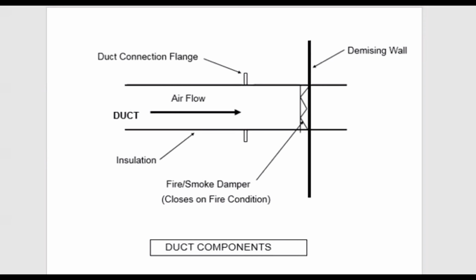All right, so if it's 50-degree air that's coming out 5 feet away from where you pass through the cool water, you don't want that temperature to be 52, 53, 54, and onwards going up. So we have to maintain the speed of the air. We have to maintain an insulated duct so that we can control those temperatures within it and not lose too much of that cool air.